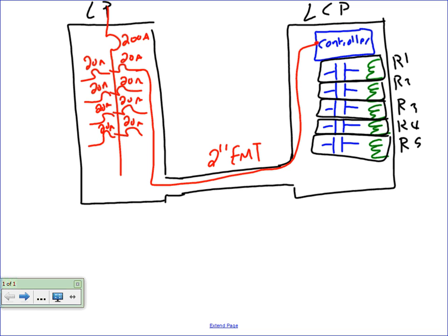So what do you think this circuit did? It powered the controller. That's just to power the brain, like your laptop has to work. You have to take a 20 amp circuit to power the controller panel. I'm showing the phases. What do you expect to go with this? Another wire: neutral. I'm not showing the neutral. Maybe I should show a neutral for this one, because the rest of them don't need one. So I'm going to show a neutral coming from here, sitting somewhere where the neutral is. So hot and neutral, a 20 amp circuit to power the controller. Is the controller powered now?